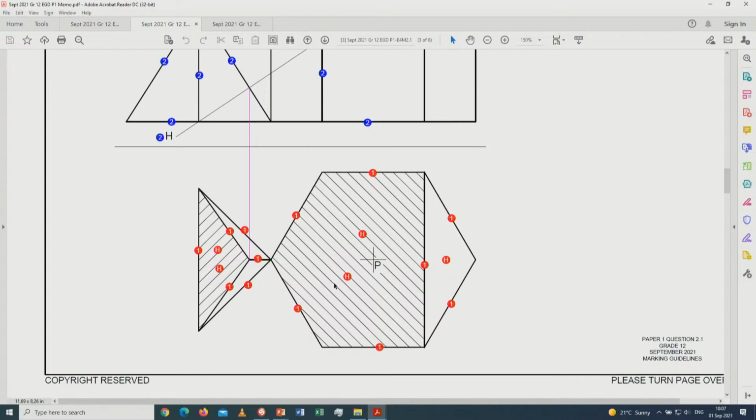All right, so 45 is not compulsory, but teach the learners to do it at 45 degrees, because you can alternate between 45 directions much easier with your 45 degree set square rather than struggling with where am I now with 60 degrees and those types of things. And the second thing is that these lines are already on 60 degrees, so it's maybe good advice to go for 45 degrees. All right, so that is preferable.